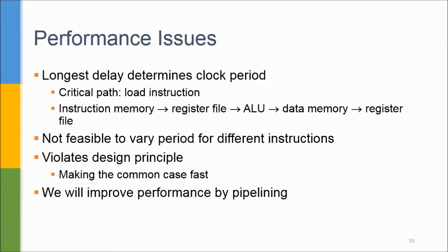The penalty for using the single clock cycle design with a fixed clock cycle is significant but might be considered acceptable for this small instruction set. Historically, early computers with very simple instruction sets did use this implementation technique. However, if we try to implement floating point units or an instruction set with more complex instructions, then the single cycle design would not work well at all, because we must assume that the clock cycle is equal to the worst case delay for all instructions. It is useless to try implementation techniques that reduce the delay of the common case but do not improve the worst case cycle time.